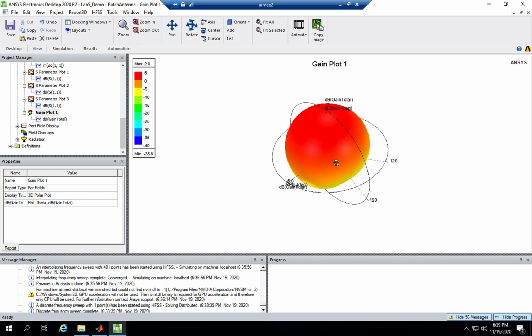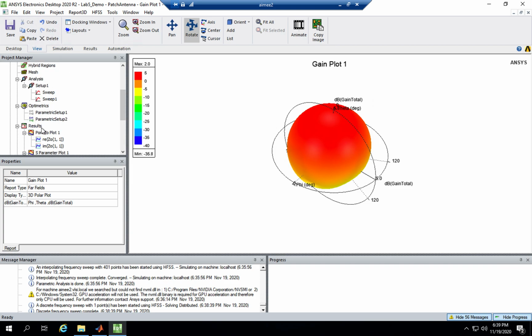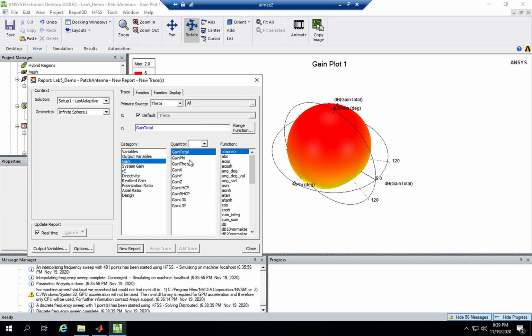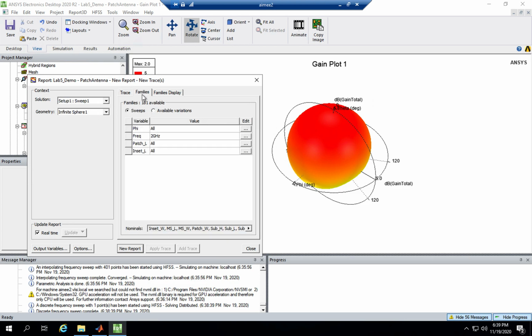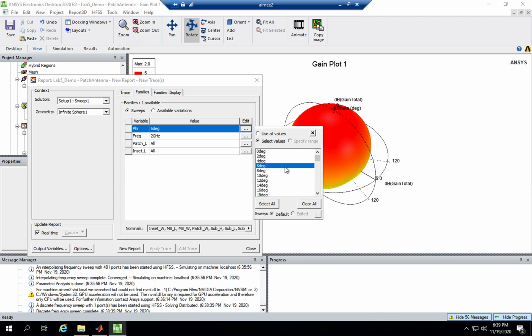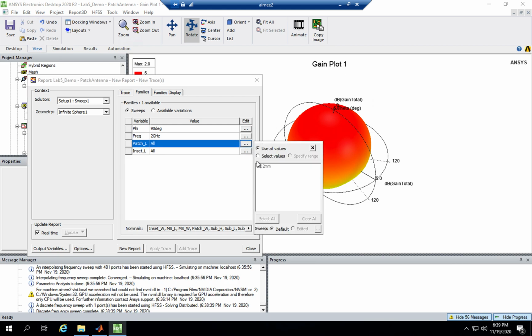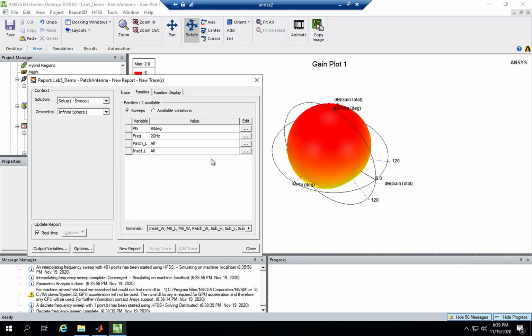All right, so now we want to look at the radiation pattern cut in the phi 90 plane. To do that, we can go under far field and choose rectangular plot. So co and cross polarized gains, as you remember, phi and theta. One of them is co, one of them is cross, and we'll see which one is which in a second. Of course, we're going to plot that at 2 gigahertz, and we want to plot it in phi 90. And the length of the inset, there should only be 1, which is the one that we just found.